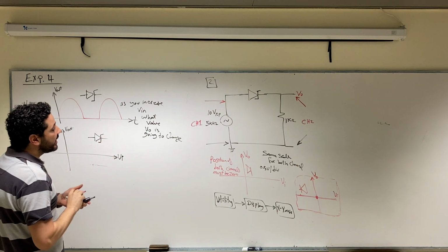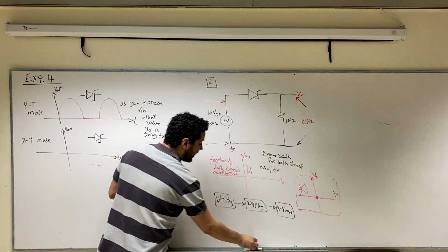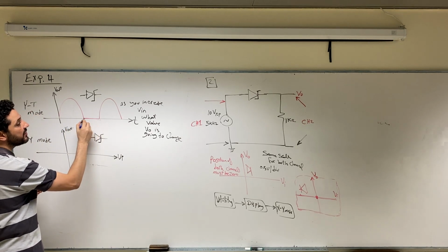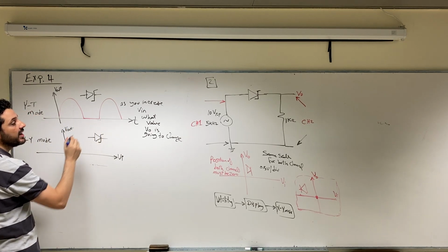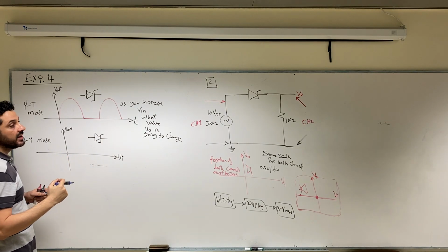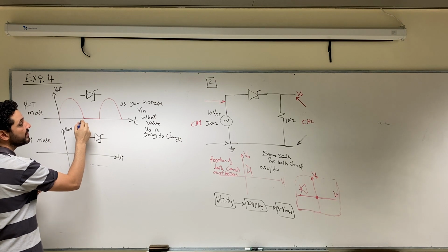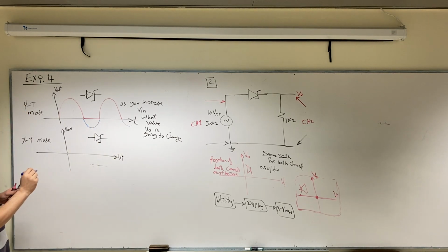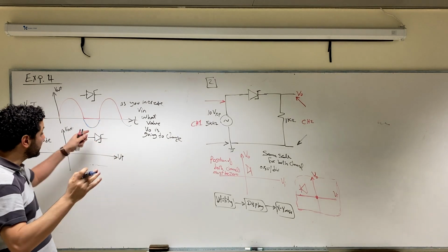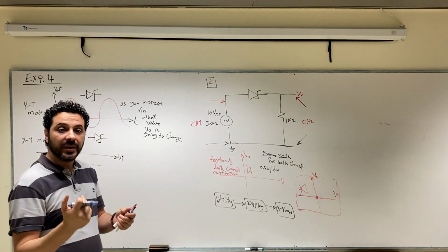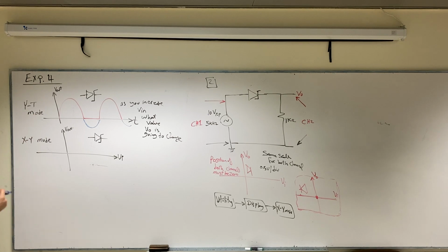While if you increase V input more, what happens is that instead of having 0 V output in the negative half cycle, the Zener diode is going to break down, and then V output is going to give you something in the negative half cycle. I will not give you the exact result here, but I will leave it to you to do by yourself, and see during the implementation.